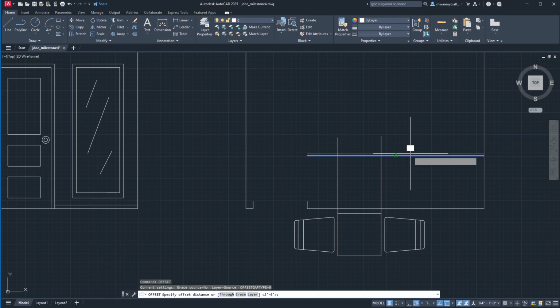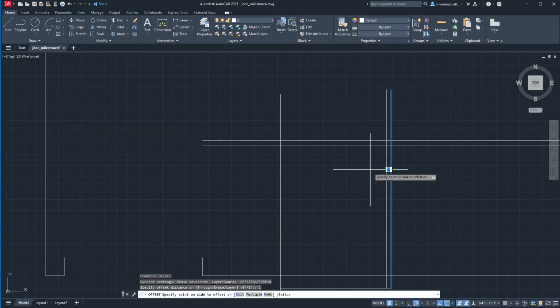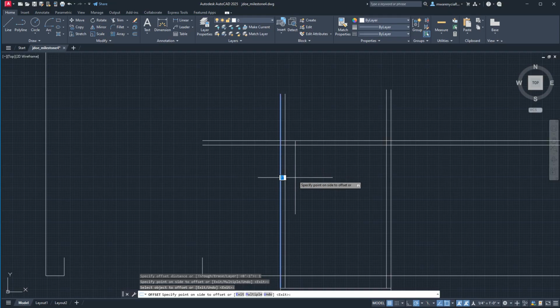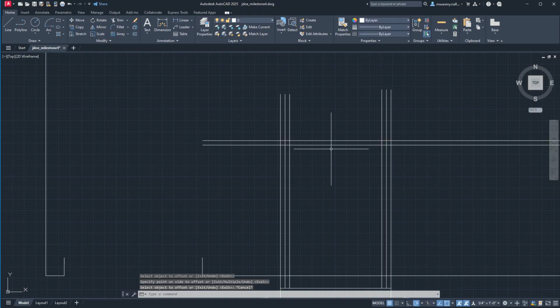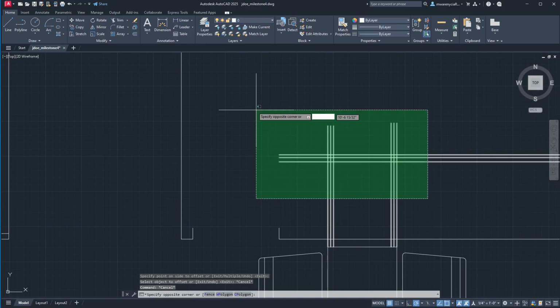We'll do 1-inch thickness, and then we'll offset these 1 inch in. So same setting as the nightstand. And then just to make it a little bit fancier, we'll do an offset of 1.5 inches. And this will be just a little brace inside of that table.